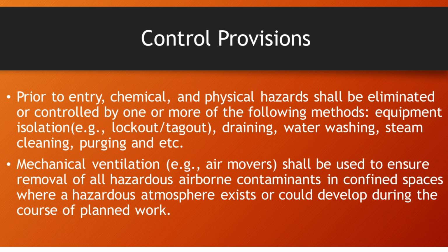Prior to entry, chemical and physical hazards shall be eliminated or controlled by one or more of the following methods: equipment isolation, for example, lockout tagout, draining, water washing, steam cleaning, purging, etc.